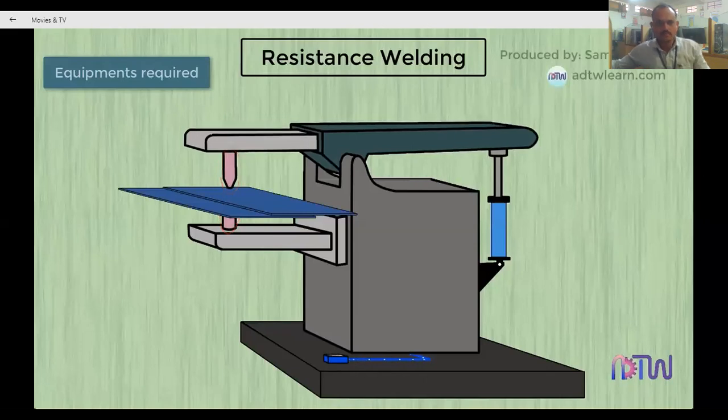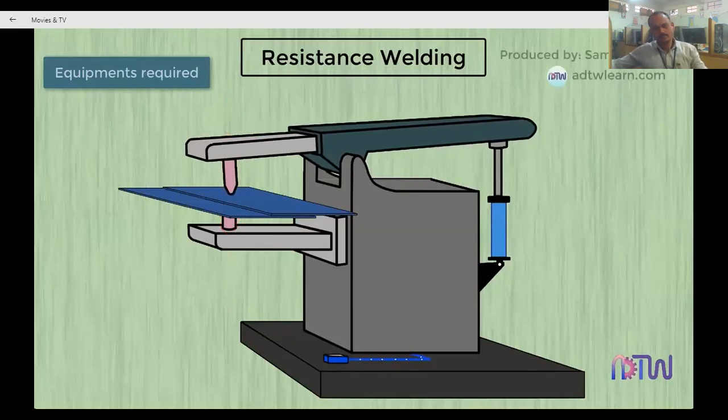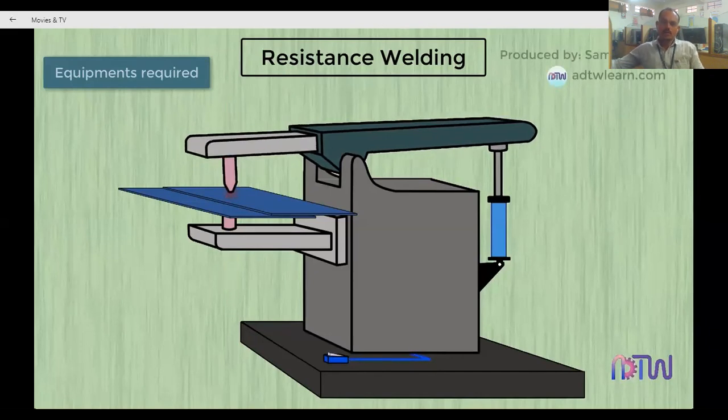These electrodes are held in pressure against the pair of workpieces to be spot welded with the help of tongs. The current flows from the tongs to the electrodes, as copper is a good conductor of electricity, but faces resistance at the point of contact between the two workpieces. This resistance generates the heat at metal-to-metal interface and causes the two metals in contact to melt. Then the pressure causes the molten metal to fuse together, and thus a solid bond is formed.